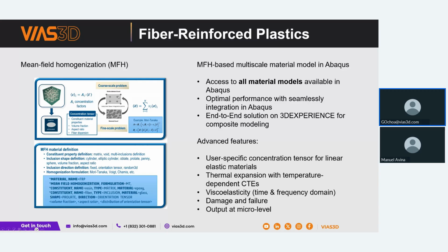So we start including in the material points or integration points the behavior of the fiber, and then on the material points we define some behaviors like the constituent material properties, the volume fraction, aspect ratio of the fiber, and then we perform a volume average operation so that will define the entire behavior of a single element.